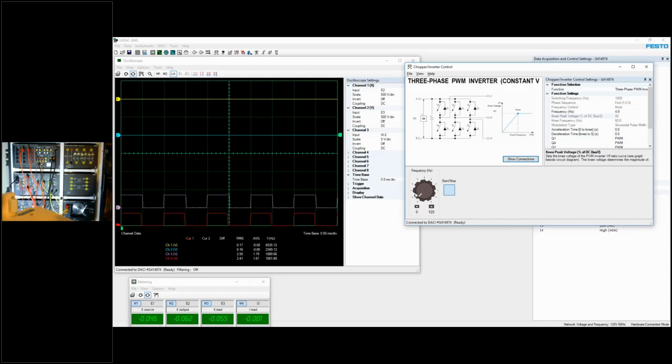Of course, here I'm not going through the theory with you, but the whole course goes through this theory in detail: the different signals sent to the different pairs of transistors and how they mesh together to produce a 3-phase output. So the students really learn how this works. And of course, if I want to increase the speed of the motor, I just increase the output frequency of my inverter here, and I can even go above 60 Hertz, 72 Hertz now, for a speed of approximately 2100.